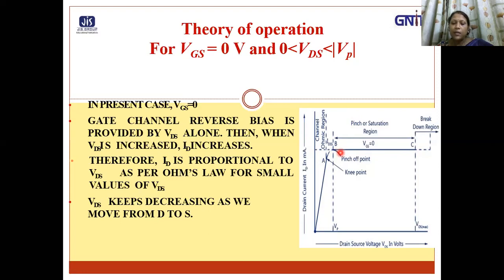The SS in IDSS indicates drain to source saturation current, with the gate shorted to source. Gate is shorted to source to make sure that VGS equals 0. This current is also known as zero gate voltage drain current.